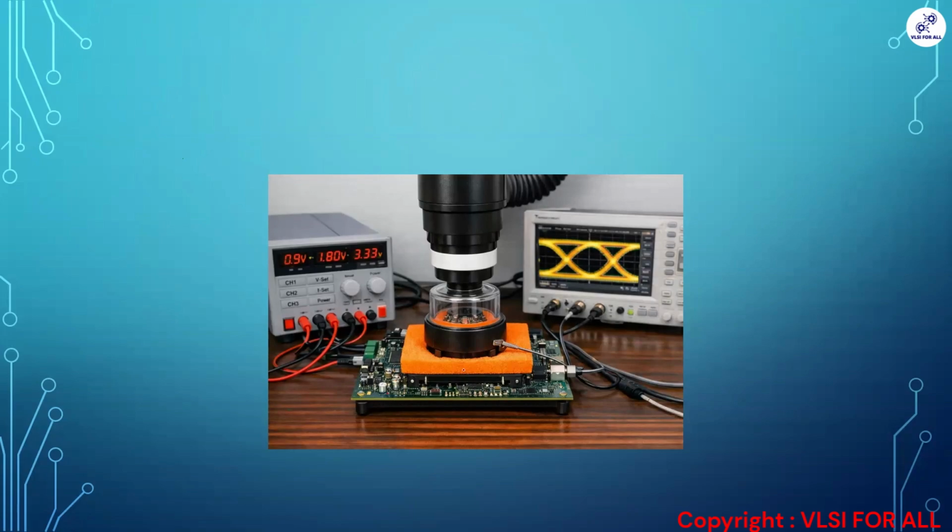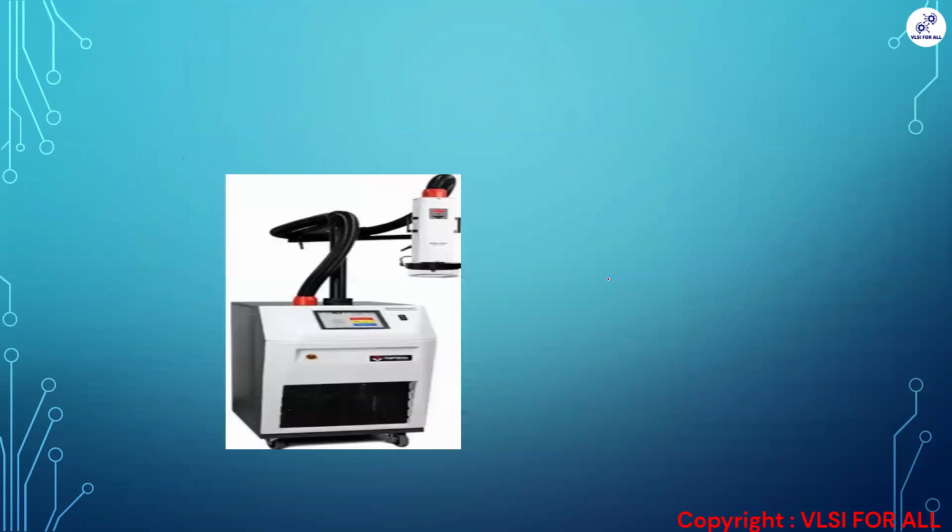We'll keep that in the center. We'll be having the SOC. We'll cut that sponge in such a way that we keep the thermal cap sourcing the temperature on the SOC. Once we set up this setup, we'll set the temperature, we'll set the voltage, and we will run using the trace 32, and we'll see the corresponding signals here. This is how the overall Thermostream will look.